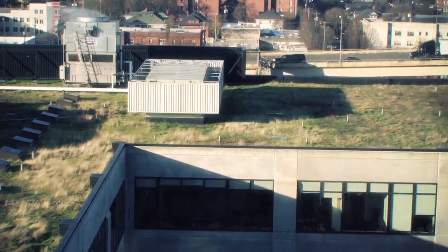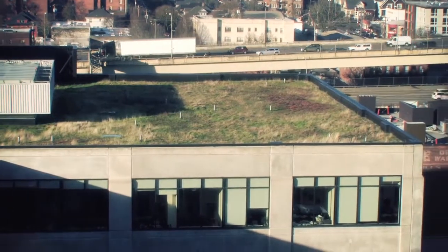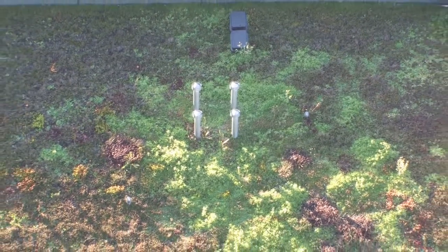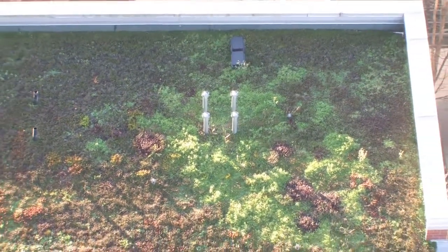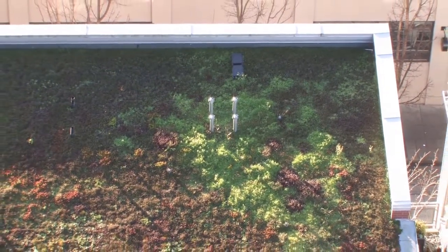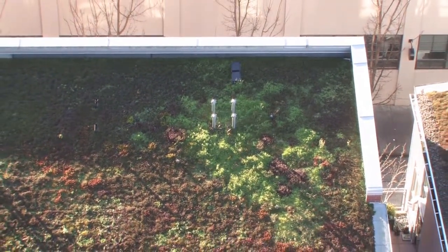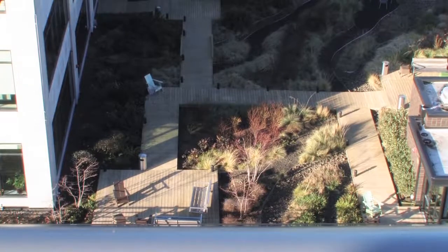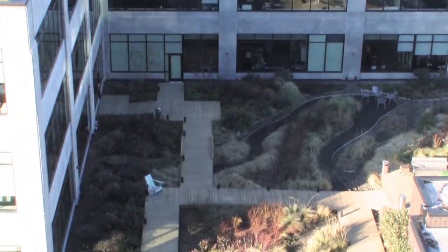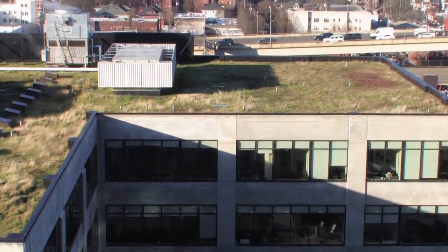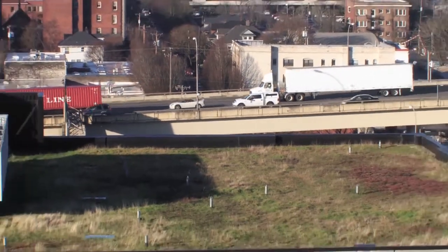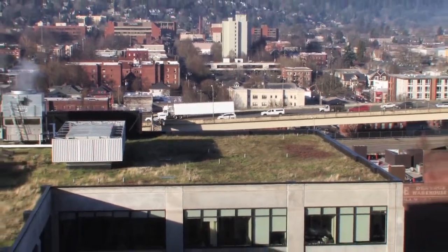Vegetated roofs consist of an impermeable roof membrane overlaid with a lightweight planting mix with a high infiltration rate and vegetated with plants tolerant of heat, drought, and periodic inundations. In addition to reducing runoff volume and frequency and improving runoff water quality, a green roof can reduce the effects of atmospheric pollution, reduce energy costs, and create an attractive environment. Green roofs have reduced replacement and maintenance costs and longer life cycles compared to traditional roofs.